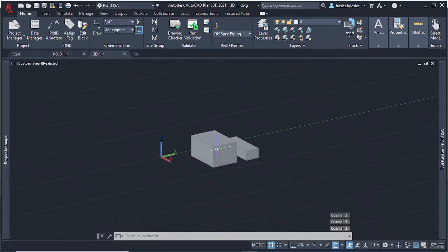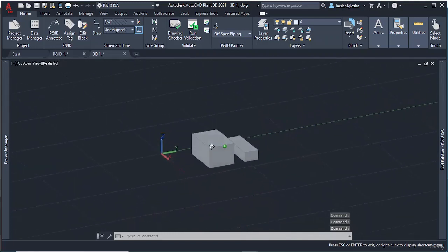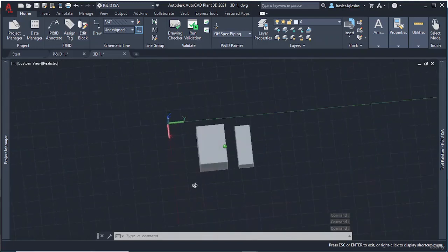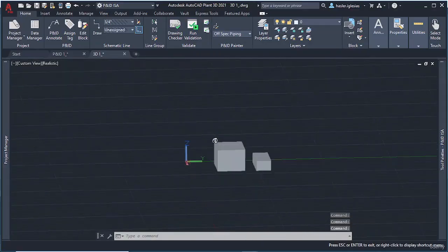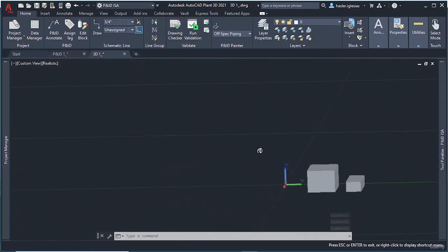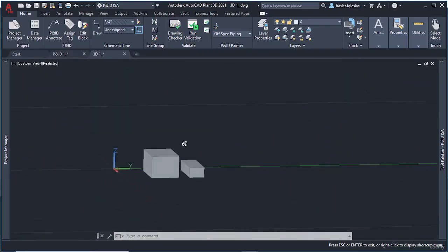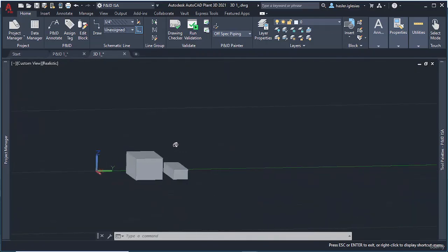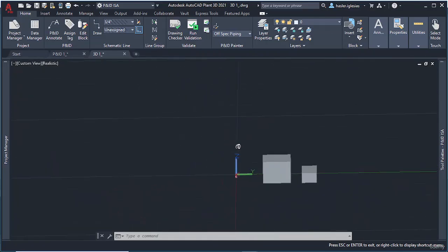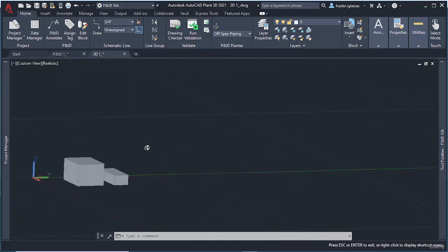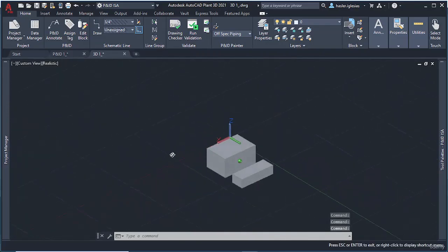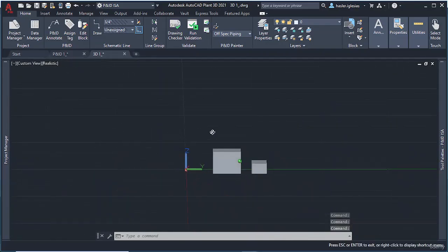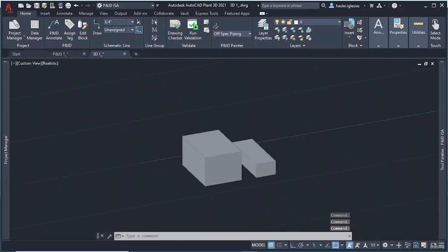And to rotate, I have to press Shift and press my scroll button, and that allows me to rotate in 3 dimensions as we are doing right now. Okay? Look, Control allows me to rotate, but maintaining my point of view. I'm rotating with Control pressed and the scroll button pressed. Okay? From side to side or from up to down. But if I rotate with Shift, I can rotate in all directions. Okay?